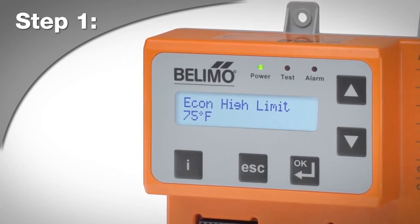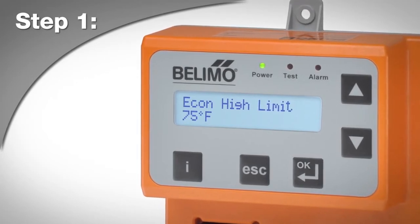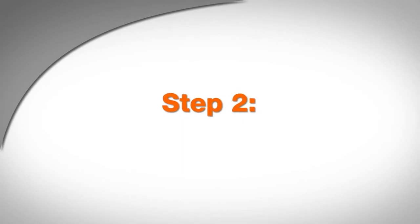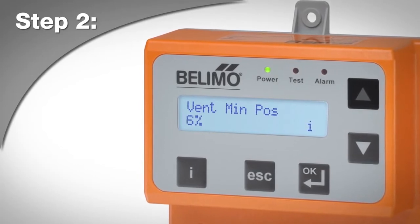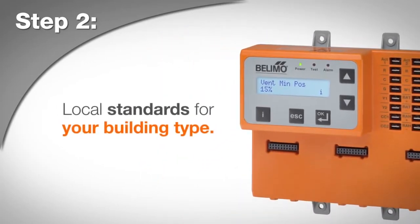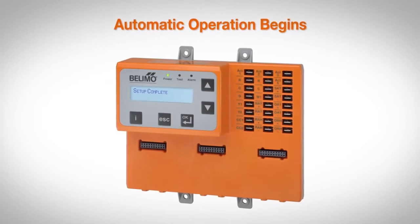The Zip Economizer automatically configures the free cooling high limit changeover temperature or enthalpy setting. Step 2. When the ventilation minimum position submenu displays, press OK and set the percentage of fresh outside air for ventilation in accordance with local standards for your building type. And that's it. In 30 seconds, the automatic operation of the Zip Economizer begins.